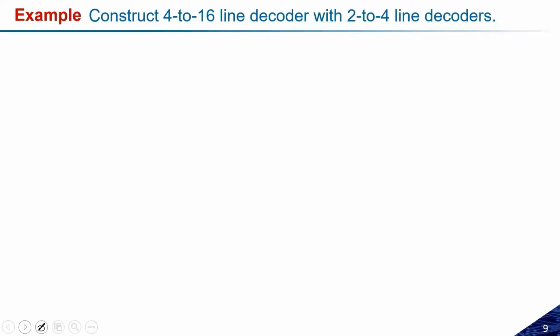Okay, let us try to apply the formula. So Jayant has given some response. Let me check. How many decoders do we need? See here, this 16 is the M. This 4 is the N. So let us try to calculate N1. N1 is equal to M divided by N, and that we are getting 4. So 4, this is the first stage decoders.